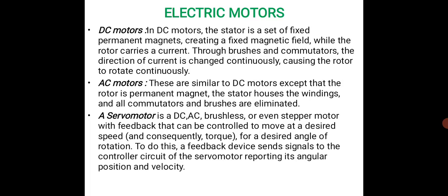The stator houses the windings, and all commutators and brushes are eliminated over here. And coming to the servo motor, it is a DC, AC brushless or even stepper motor which will have a feedback mechanism which can be controlled to move at a desired speed. And obviously once you are able to control the speed, you can control the torque. So for a desired angle of rotation, I can move it.